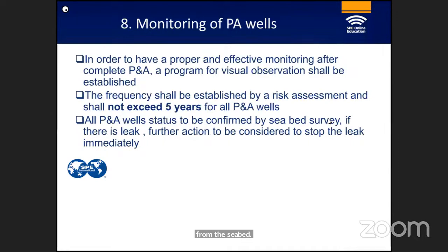So the last point is monitoring of P&A wells. In order to have proper and effective monitoring after completing the P&A, a program for visual inspection shall be established. The frequency shall be established by a risk assessment and should not exceed 5 years for all P&A wells.